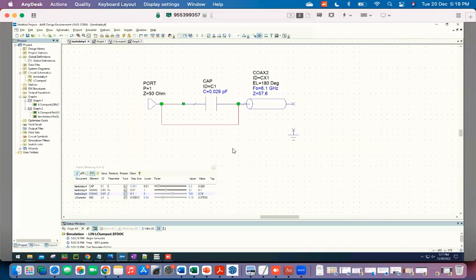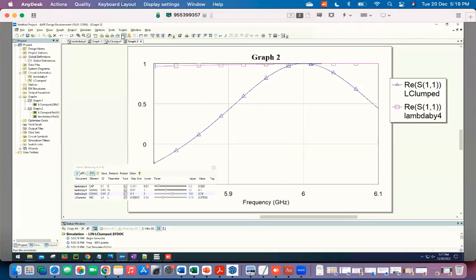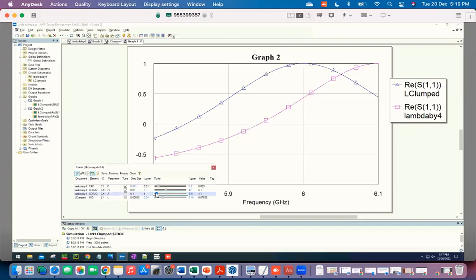I'm going to just short circuit the capacitor so that it's not there. Now, the resonance, of course, becomes very broad. Remember that when we were in this position earlier, I changed the characteristic impedance and I showed you it only got narrower. Right now, the frequency is off because I changed it.